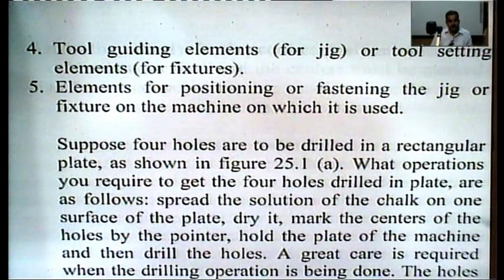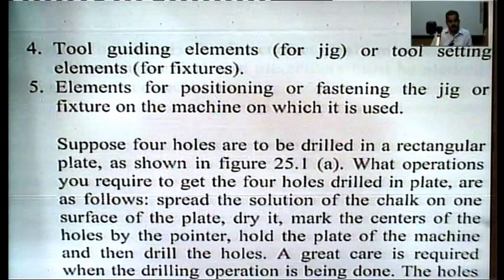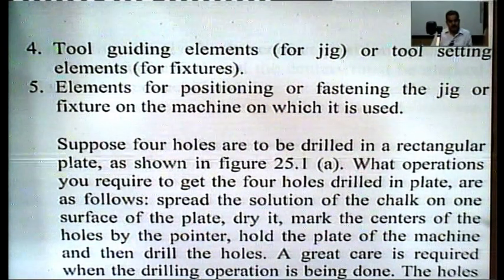It must have tool guiding elements, because in case of jig, tool must be guided, so it must have some guiding elements, and in case of fixture it must have some tool setting elements.